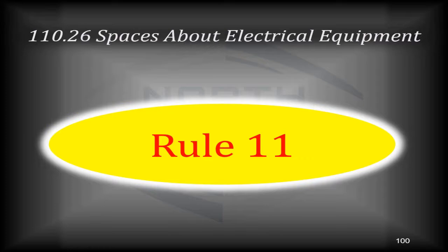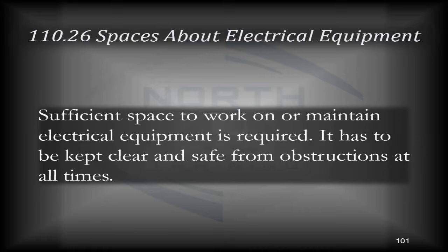110.26, spaces about electrical equipment. Rule number 11. 110.26, spaces about electrical equipment. Sufficient space to work on or maintain electrical equipment is required. It has to be kept clear and safe from obstructions all the time.